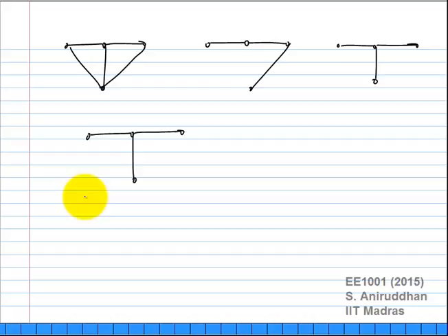Now what we are going to do is take this tree and start adding branches such that they complete loops, representing what was a connection through an element in the original graph. You can't draw it arbitrarily. So in other words, I can't draw a link like this because this was not contained in the original electrical network. What are the two options? I can draw one here, I can draw one here.